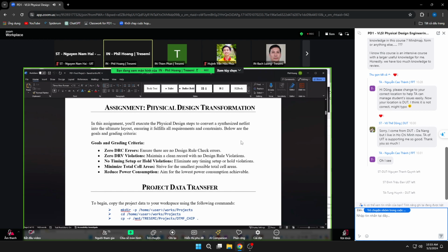And then if you meet the speed, if you have less cell area, you have less power consumption, or you might not, because the power consumption also has the dynamic part of it. So the total cell area can affect your static power, but dynamic power depends on different things, like slew rate, the caps of heavily switched buses versus not. So the total power consumption is another measuring stick.